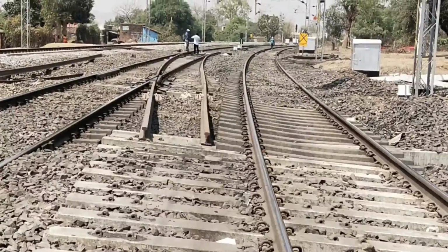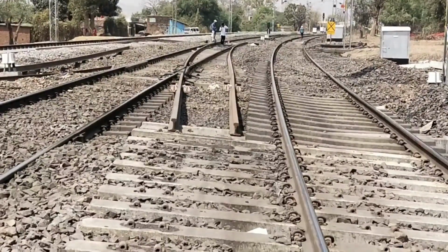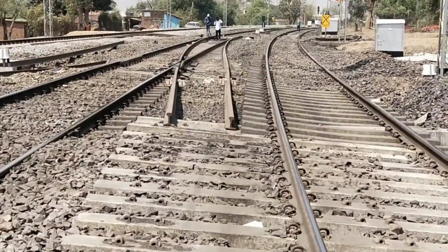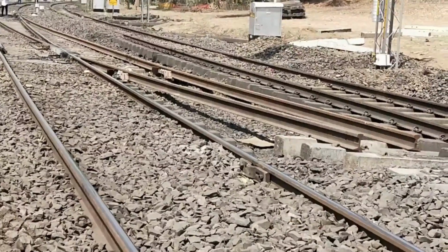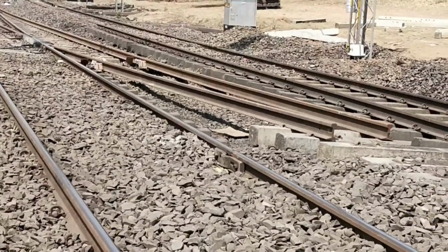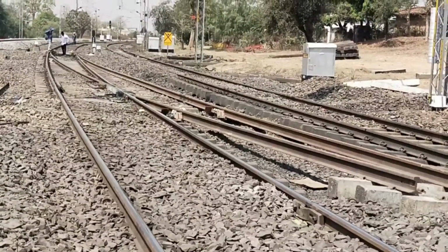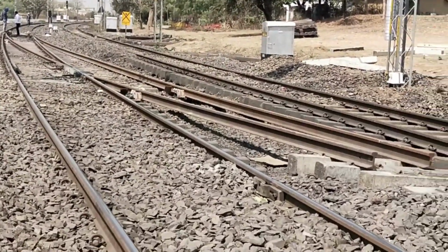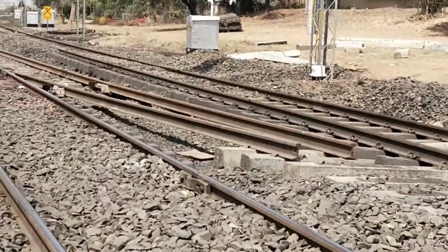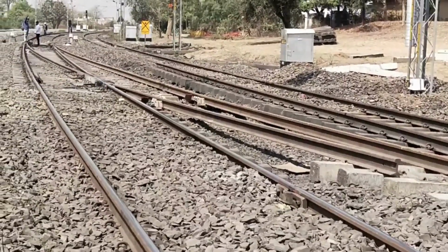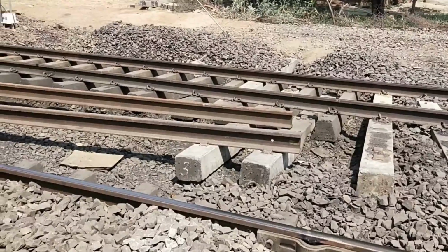At some other location, turnouts were initiated for laying a crossover in existing curved tracks without making 0 superelevation. In one curved track, the full turnout has been laid, whereas in the other curved track it has been inserted only up to sleeper number 65. Finally, this crossover has not been connected.